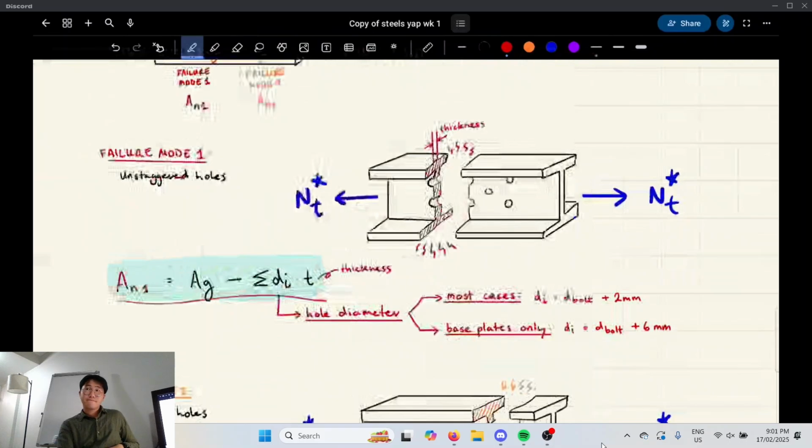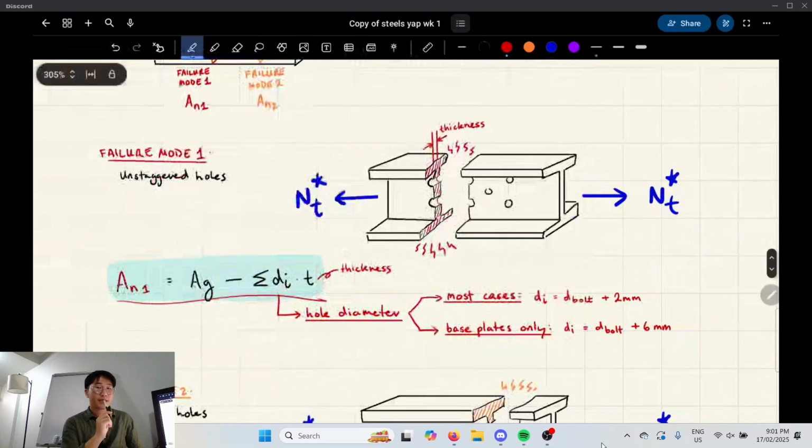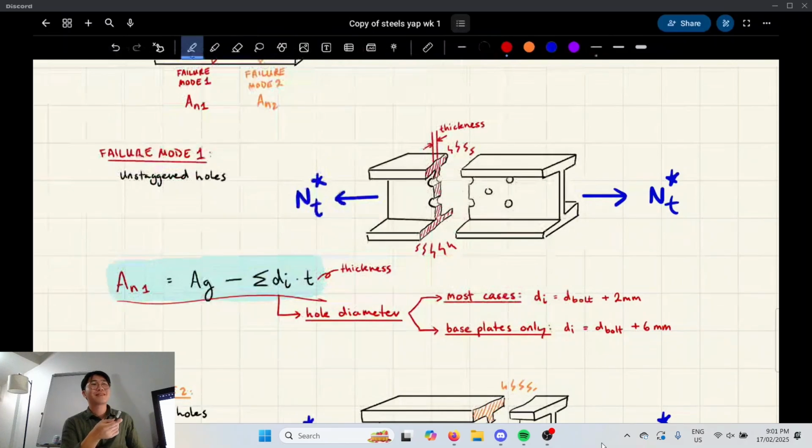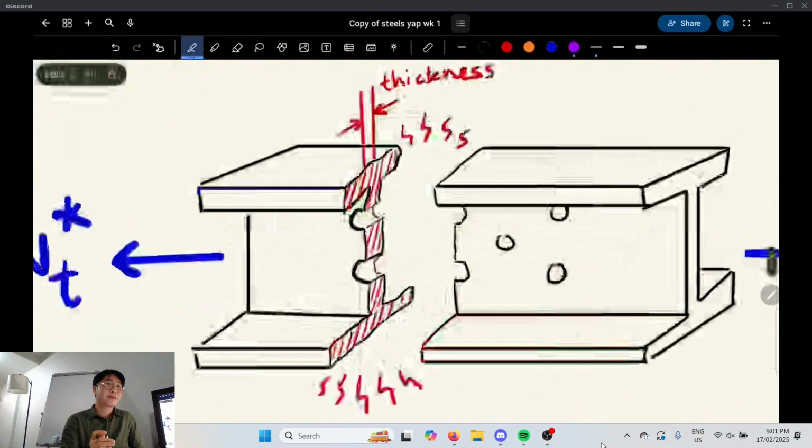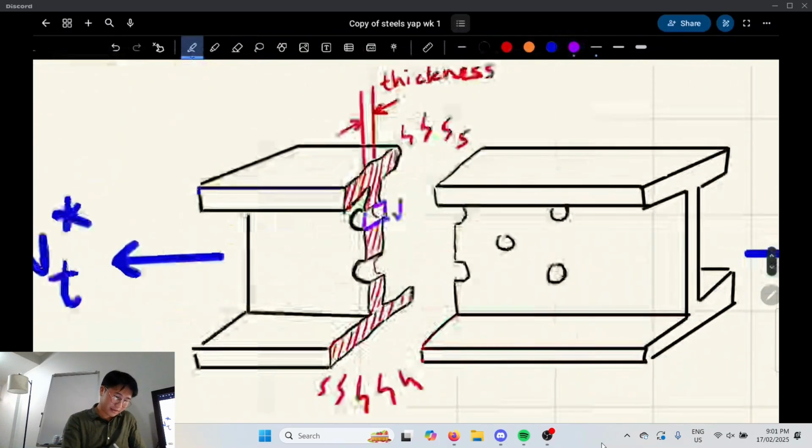Because in year 1 when you draw the cross section of this shape, it's a rectangle. Yes, pretty much. Wait, is D the diameter of the hole? Yes. So why have I not done pi on 4 d squared? It's not actually a circle. It's the distance from one half of the beam to the other. You're right, it's actually a rectangle. So the whole diameter is that, right? And then we actually consider the thickness of the web in this case, but it can be on the flange.